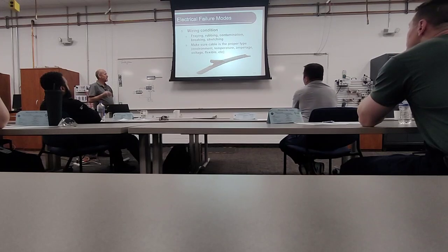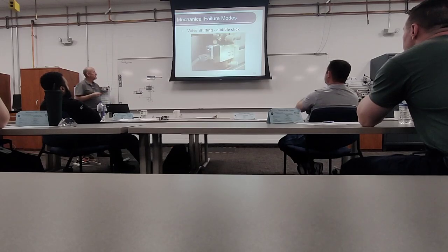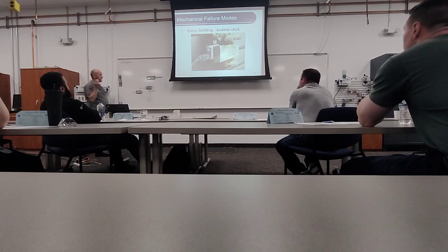Yeah, I'm not even going to get into this wire spread. If you see a coil that looks like that, you put 120 volts on a 24-volt coil. I can guarantee it. I leave this up here because it cracks me up. In most cases, you are not going to hear any click on those valves, especially on most plant floors I've ever been on. The visual indicator is your best indicator that you're getting the signal there. Again, not 100% signal, there's something working with it.